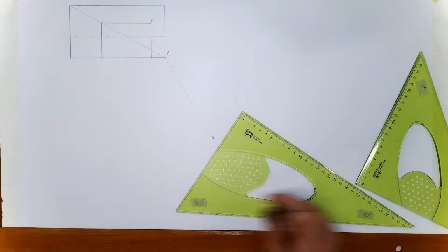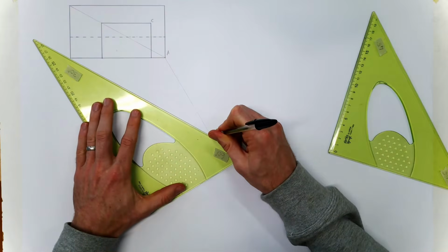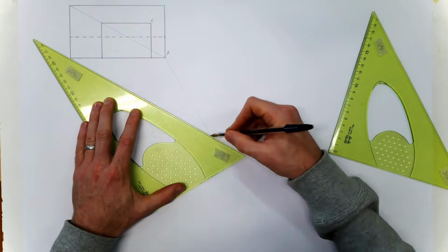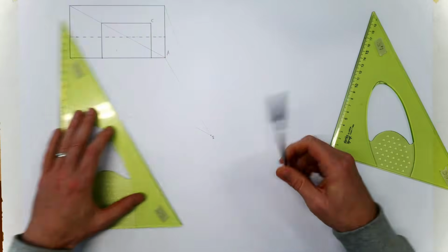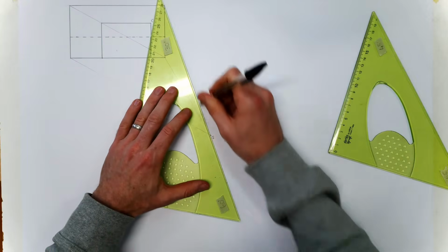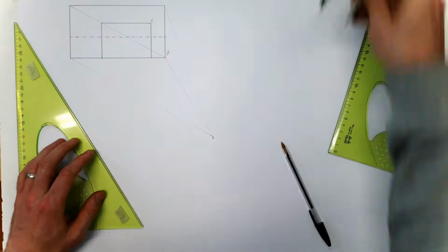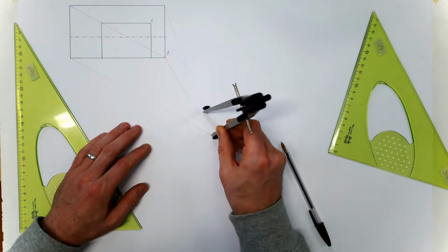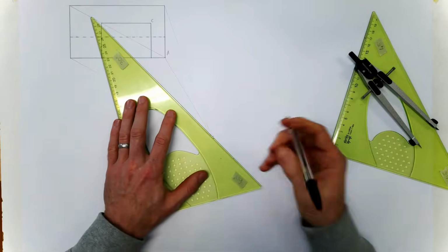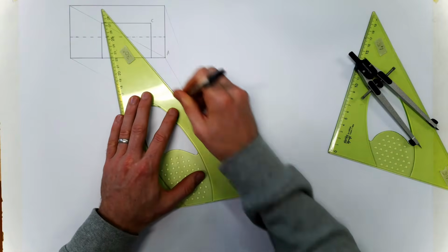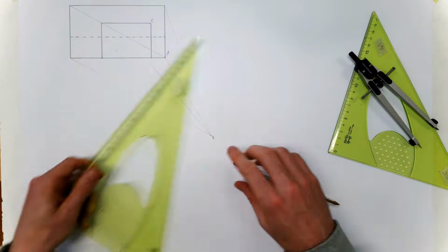Our setup for these questions is always going to be the same. So let's go for that. Outside point, join back to spectator. Outside point, join back to spectator. We want to find the direction we're viewing, so we need to bisect that angle. So compass, swing an arc, keep the same distance arc, swing it twice, and we have the direction that we're viewing. Our spectator will be at 90 degrees to that.